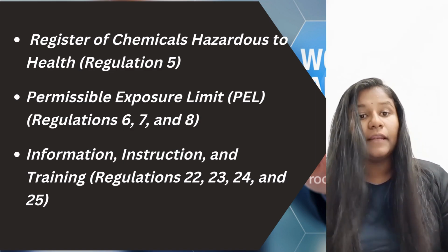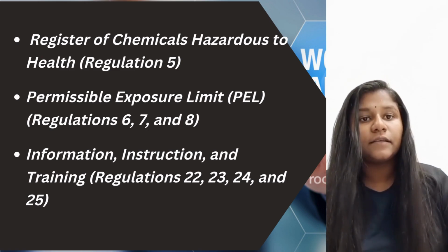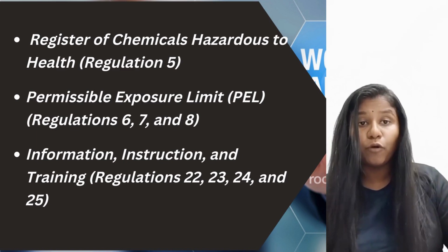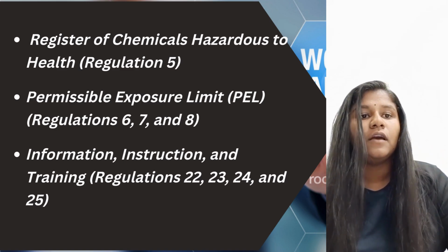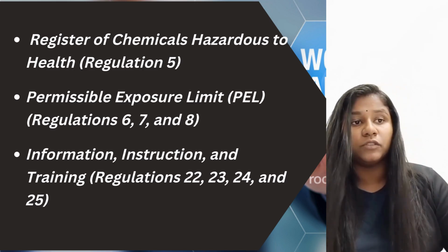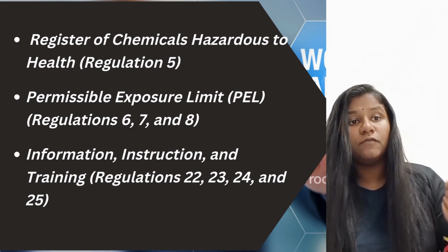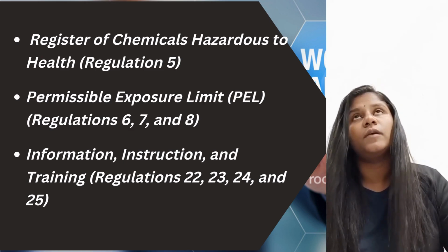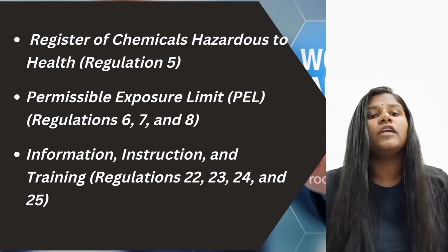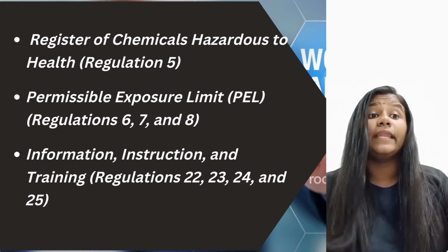And next, permissible exposure limit. Context: the PEL defines the safe exposure level to hazardous chemicals. The importance is, first, the ceiling limit, which protects against acute exposure by setting the maximum allowable concentration for short-term exposure. And next is the 8-hour time weighted average, which ensures long-term exposure stays within the safe limit by averaging exposure over an 8-hour period.